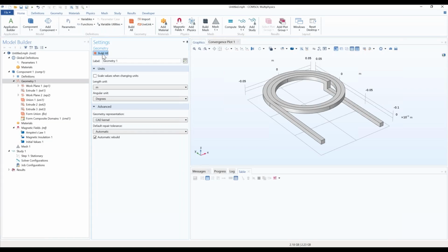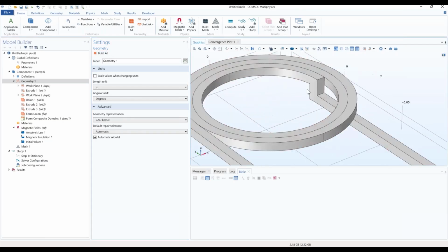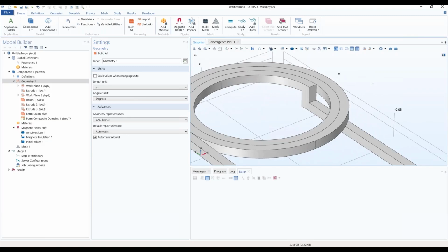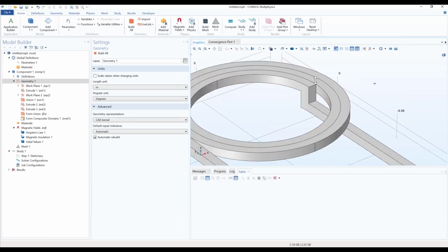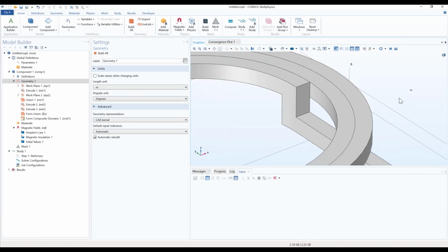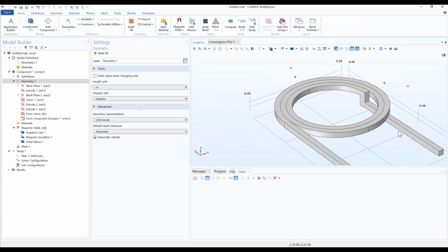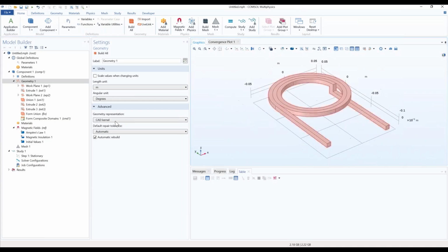Now, what we're looking at is a volumetric coil again. What makes this coil different from the ones that we looked at before, this is a volumetric coil, but you can see that the turns are actually immediately adjacent to each other. The way that we've modeled this geometry is that you have a conductor, a square conductor, and we actually don't model any gap there at all. There's no distance between these turns. So we have a very tightly packed coil. We can consider it that way.